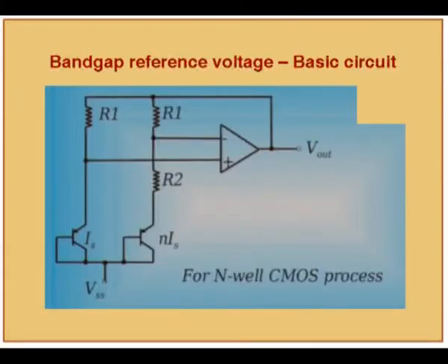Suppose if you want to generate a low voltage bandgap, one approach of course is given here. Another approach is, what they do is that in the conventional bandgap, they use transistors for mirroring currents instead of resistors. And now because putting transistor here as a mirror, they can mirror this current everywhere, right? They can have different mirrors.